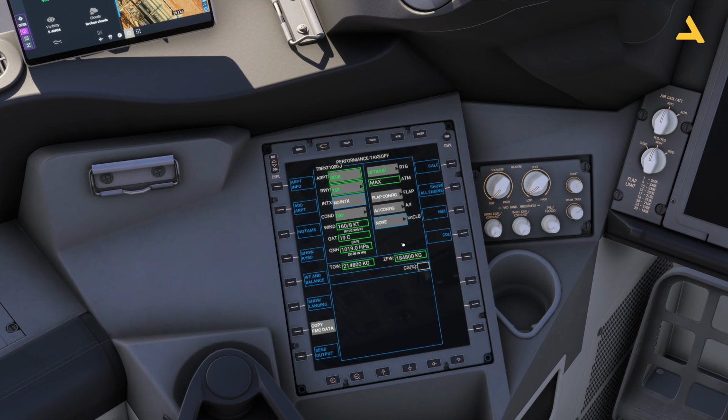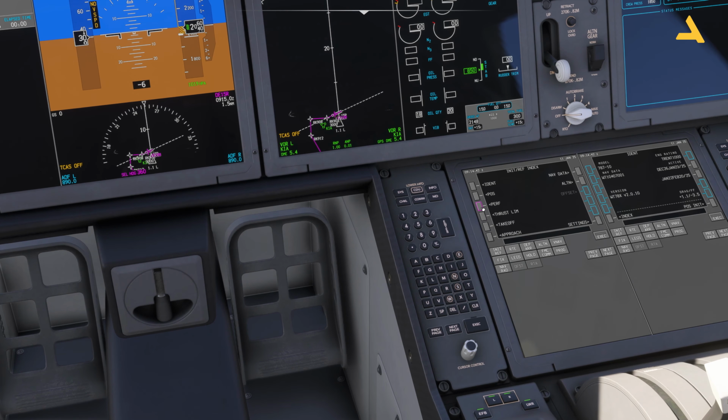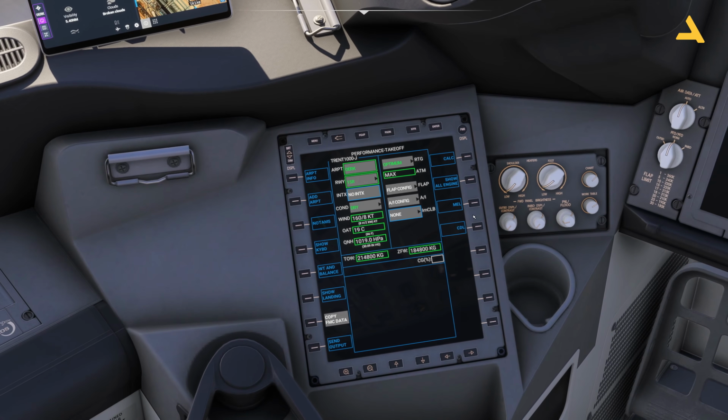That's it. As I told you before, you have this assumed temperature method, which is this. So let it do the calculation. And flaps again, you can set whether you want 5 flaps or 10 flaps. But remember, during the takeoff you need lift, and the flaps provide the lift, but they also provide drag. So that's why you have to have the optimum settings based on the weight and the fuel this plane is carrying. Anti-ice will be off because I'm not flying in icing condition. That's why I will just keep it off.